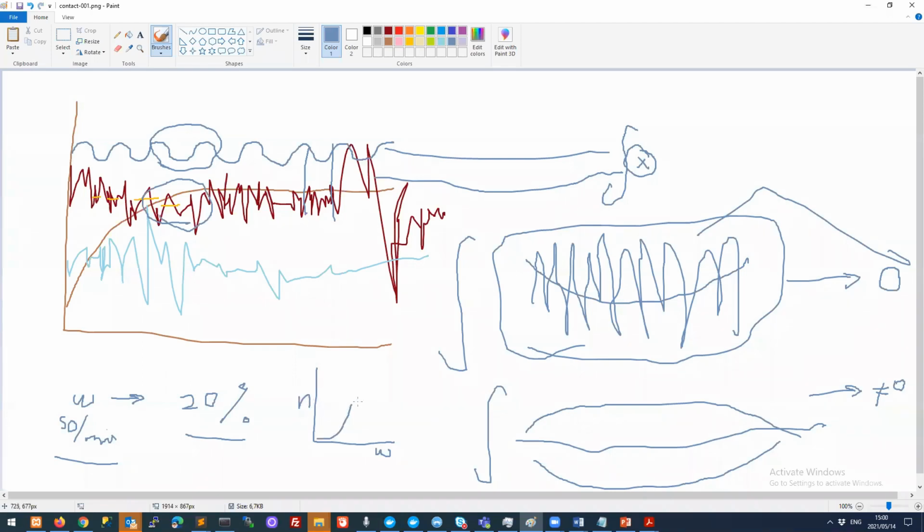So it's going to give us some distribution in frequency. And then we'll be able to say, well, my system is jumping around this frequency and around this frequency. That's really valuable information, right? You can imagine we want to create our controller. So we want to know how often this process is jumping around. And then you can say, well, on average, it jumps around at 120 per minute. And then you can start thinking about putting in a controller.